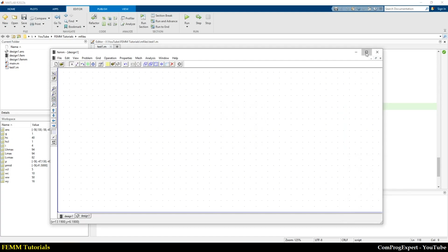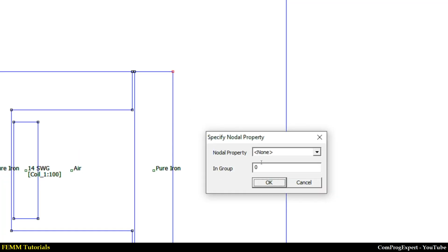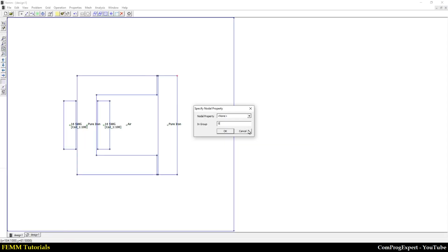We can assign an index and group objects. If I click on this point, as you can see here, we can assign the group index, in group. And then we can select the group and move components. This is better because we don't generate the model from scratch.